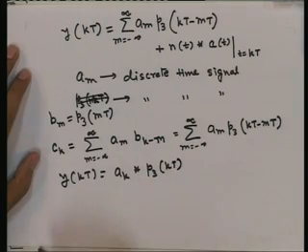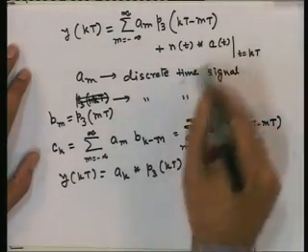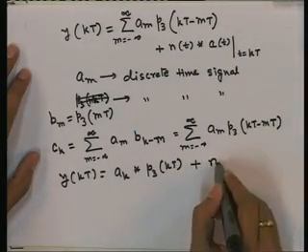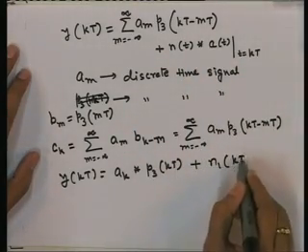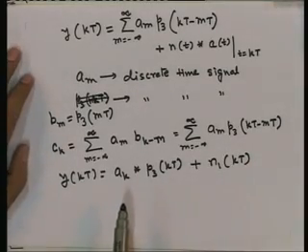So this sequence and this sequence are convolved, and we take the kth sample of the convolution, plus the noise, call this signal n1(t), then n1 at kT. This is the sampled value at kT.